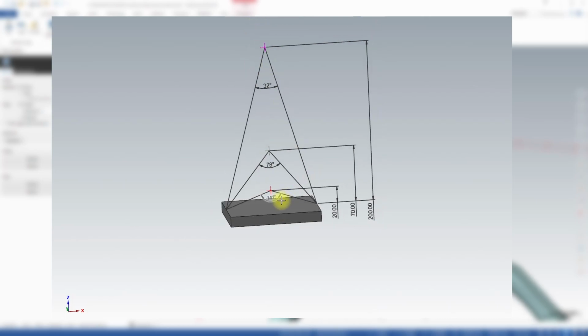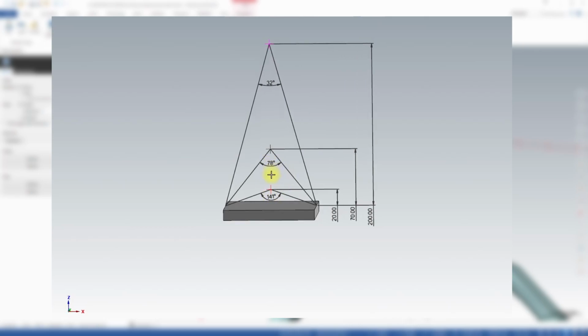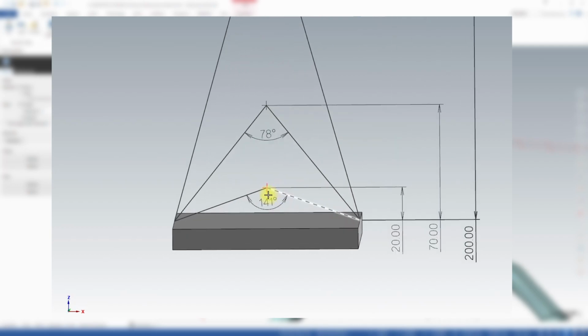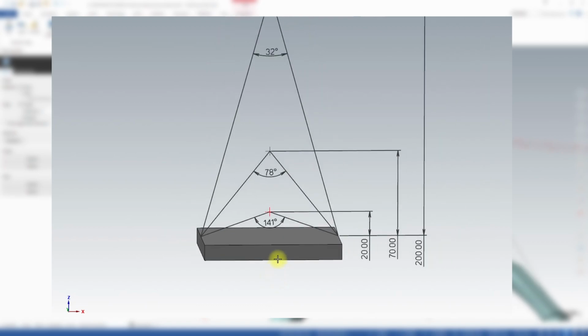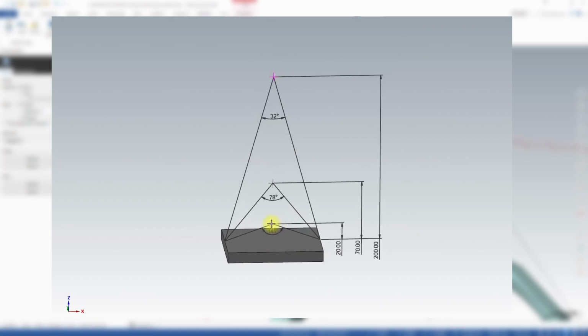Sometimes we have to be close to the surface. So just bear in mind, generally the farther away from the surface you are when you are controlling the tool axis from point, the less angular action you get. And the finish on your part will look much better.